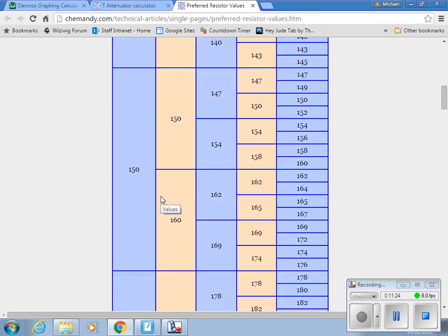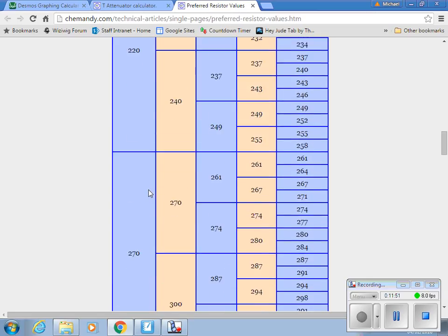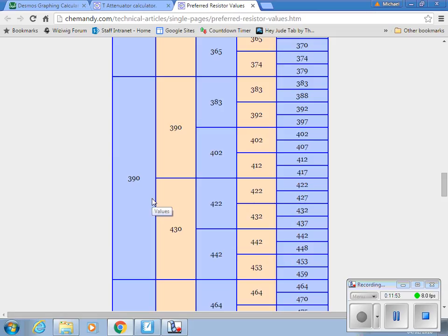That's got a, well, in this place you'd get one with a 5% tolerance. Yeah, exactly. But because in this case you're dead on a preferred value, you might be better off going with the Pi design, because you get closer to your design values. What was the other one? 375 and 1500. So you could pick a 390 for that. That might be closer than the T design.